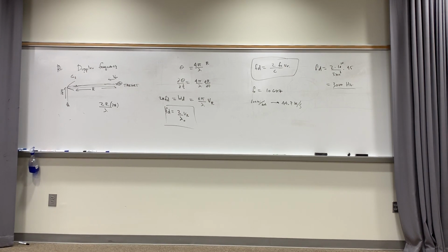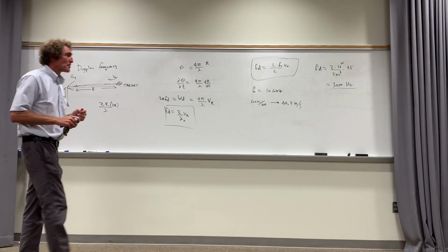What do we do? Well, we multiply it by another thing that's got cosine of 2 pi times 10 gigahertz t, because then you get the sum and the difference frequencies. Do you all remember this? Didn't you have a radio lab here? All right, well, when you get the difference frequency, then you work at what's called the low frequency or baseband. Now you're working at just the frequency associated with the shift.